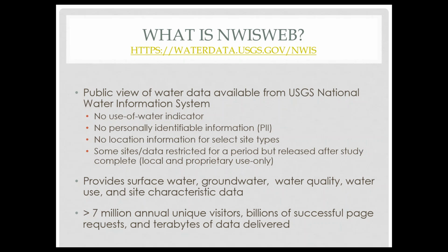So we will often put down a borehole camera and we'll look at the integrity of that well. Or we may pump the well and say, it looks like it's got a good signature, it's pumping, it's not clogged. So you want to consider, again, the location of the well, the construction of the well, the site characteristics.